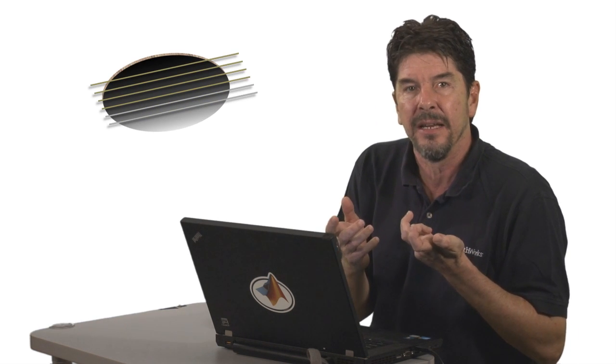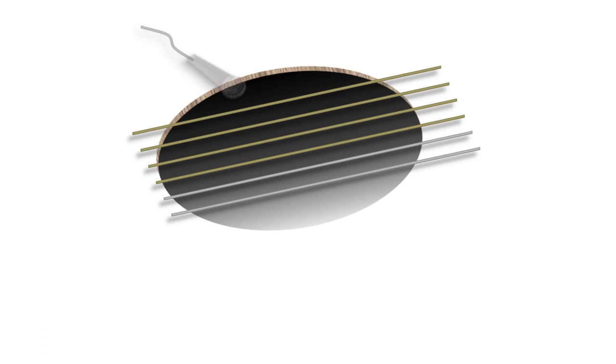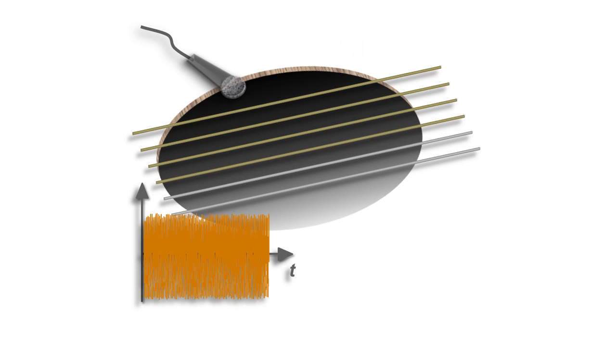simple examples. Let me start with an acoustic guitar, and please forgive my overly simplistic drawing back there. If we place a microphone anywhere close to its soundboard and we pluck one of the strings, the vibration will resonate in the guitar cavity and will produce a sound wave that will be captured by the mic. Looking at the time trace of that signal from the microphone gives us very little information about what is going on. Only when we look at that same signal on a spectrum analyzer or we take an FFT of it, we are able to see an amplitude peak at some frequency. This frequency happens to be the underlying tone that forms the note we just played.